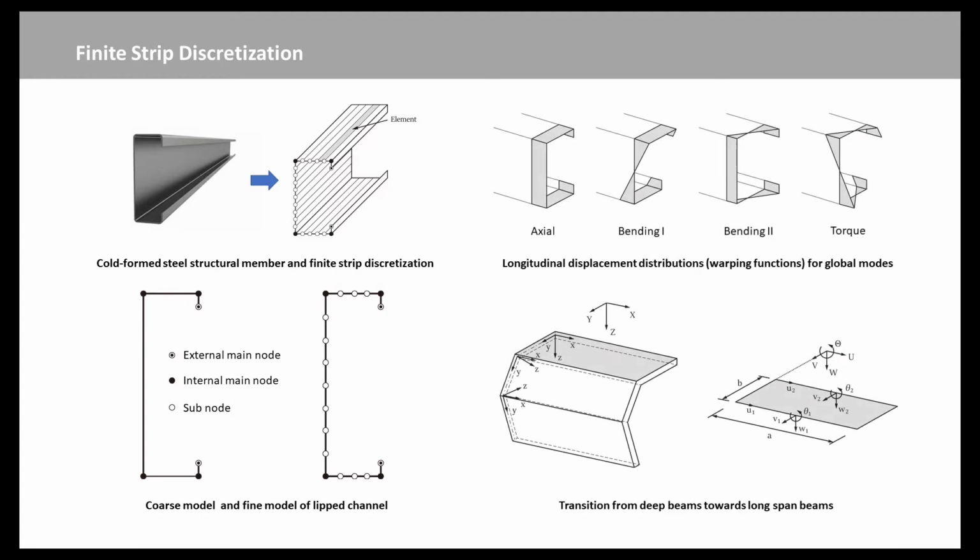In the finite strip method, a local coordinate system is defined for each strip, as well as one global coordinate system. In the global coordinate system, each of the nodal lines is associated with the following 4 degrees of freedom: the translation big U in the x direction measured at the specimen ends, which are assumed to be equal and opposite, in addition to the translations big V and big W in the global y and z directions, and the rotation big theta about the x-axis, all measured at mid-length.